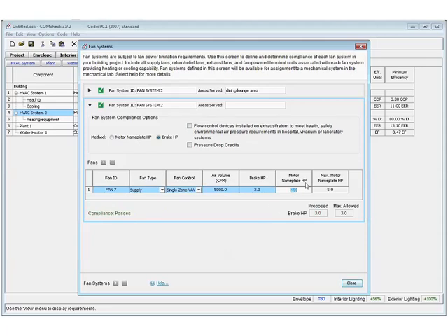With this, the maximum allowed, what drives that is the brake horsepower running that calculation. But the other thing you have to pay attention to with this method is your motor nameplate cannot be higher than the max motor nameplate. If this was 6, it would be failing, or higher than 5. So let's close out of this.